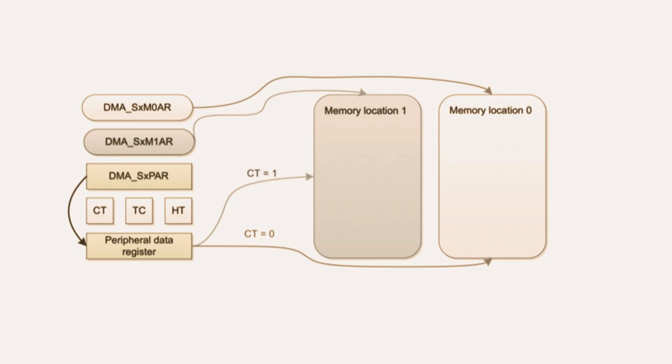But with DMA, you can configure the DMA controller to automatically collect all 16, or however many you need, raw samples from the ADC and place them sequentially into a buffer in RAM. The DMA can trigger an interrupt only after it has collected all 16 samples. Ah, so only one interrupt for the whole batch. Exactly. The CPU wakes up just once, finds all 16 raw samples waiting neatly in the RAM buffer, runs a quick loop to sum them up, performs the right shift to get the high-resolution average, and then it's done.